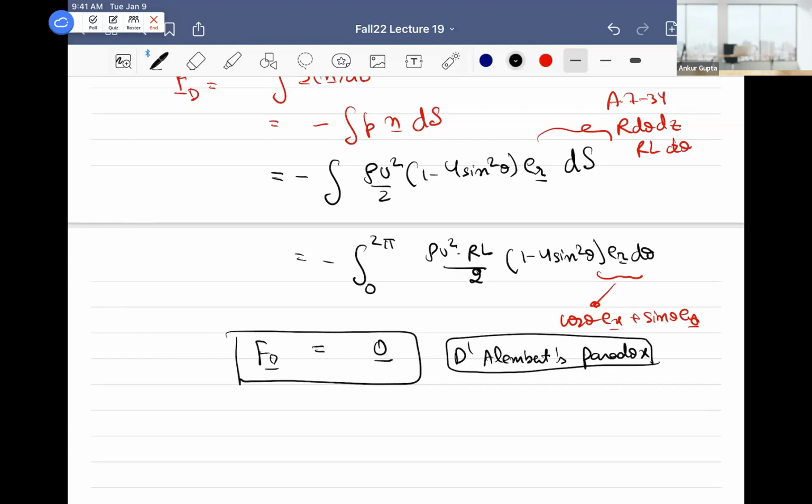Right, great. So the idea is we have assumed viscosity to be exactly zero. And there is a difference between the viscosity being small or being exactly zero, and there is no fluid in the world which has exactly zero viscosity. Because viscosity is always finite, there is always a region near the surface where there is no slip. And because we do not apply no slip, and slip causes all the change, that's called the boundary layer, right? Where you have viscous stresses always being important.